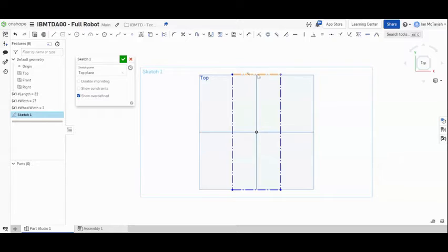Now, we haven't set the dimensions, so that's why. So we're going to set the dimensions right now. The dimension tool is this tool right here, and you can see the letter D. Always learn the keyboard shortcuts for the tools that you're going to use all the time. We're going to use the dimension tool a lot. So click the letter D, that will select the dimension tool.